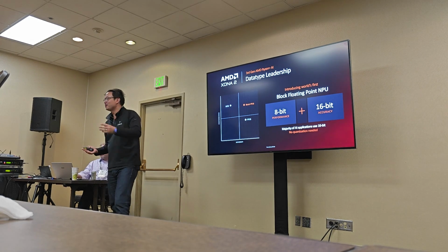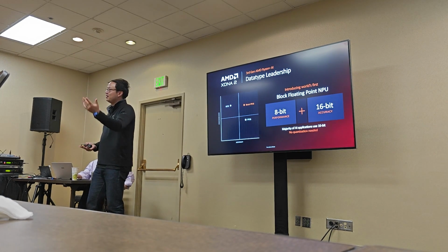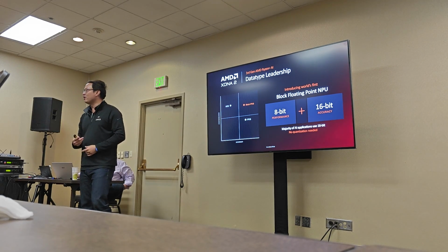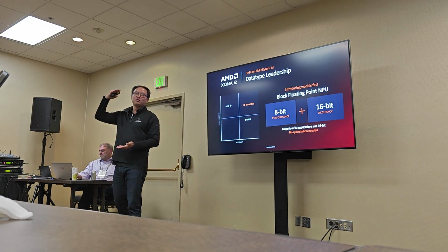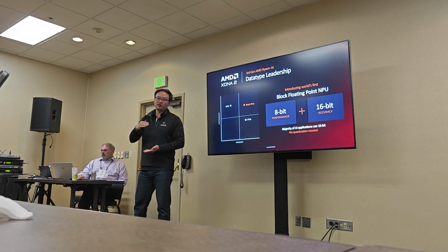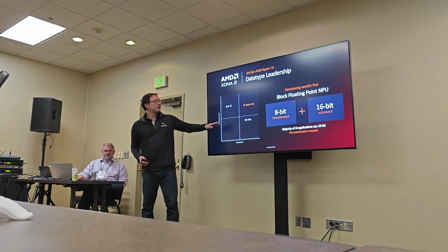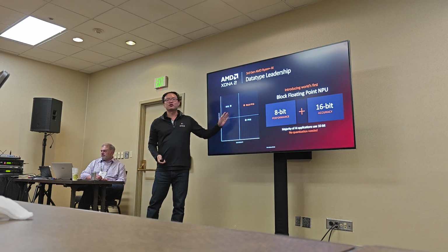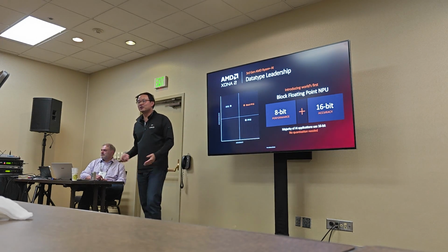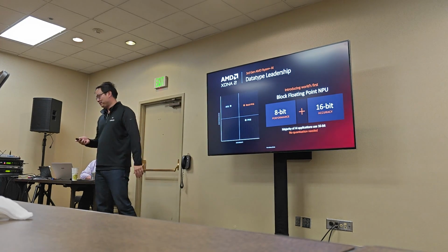So you can do the math, right? The exponent becomes 8 divided by 8. So basically 1 bit could represent all 8 numbers. So essentially you're reducing the bits from 16-bit down to very close to 8-bit, to be exact, 9, right? That's why you get the performance of integer 8, but also the accuracy of 16-bit, because you're not really losing anything for most of the numbers.